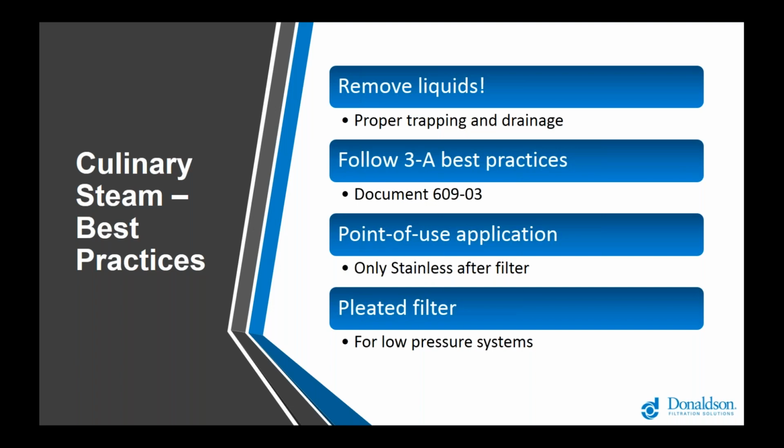And lastly, pay attention to the technologies on the market, especially when working with a low pressure application. So we usually consider those the things that are under around 15 psig. So there's not a lot of pressure in these systems to work with, and well, maybe a 3 psi pressure drop through a filter might be okay on a 100 psi system, representing about 3% of available pressure. That same 3 psi on a 15 psi system is now about 20% of the available pressure. So it's important in these applications to use something like a pleated filter with much more immediate surface area available compared to the typical cylindrical stainless steel sintered powder media that was mentioned earlier.